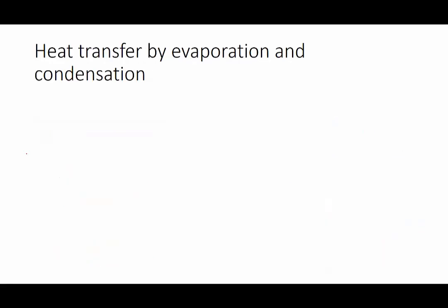Heat transfer by evaporation and condensation. You need to know how evaporation and condensation can be used to transfer heat. Starting with evaporation, the first thing you need to know is that not all particles in a liquid have the same kinetic energy. Their kinetic energies will form a distribution something like this. So if we've got the kinetic energy along the bottom and the number of particles up the side,